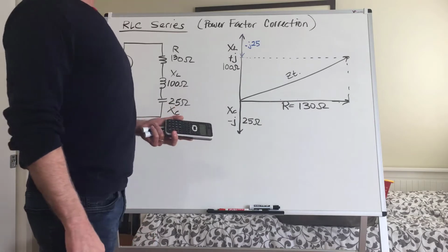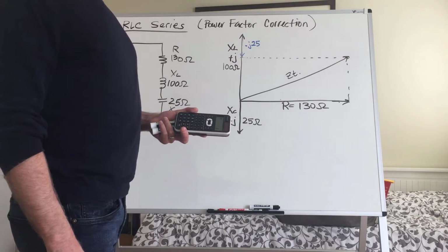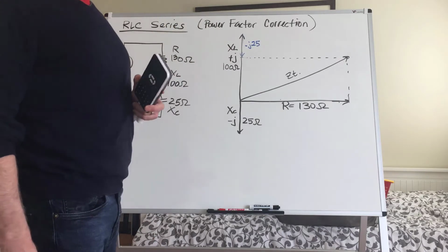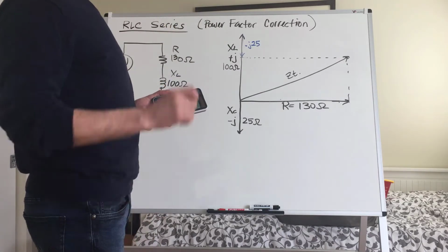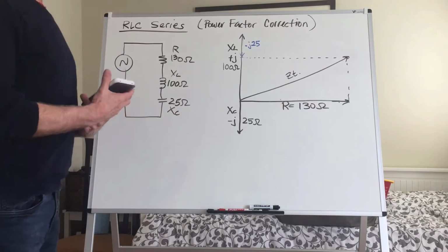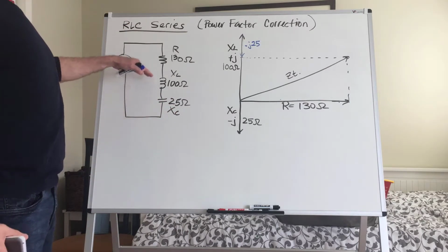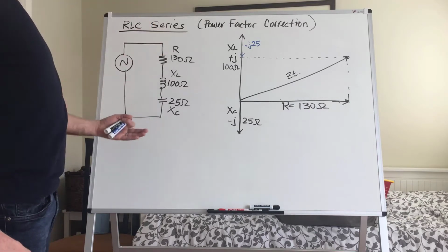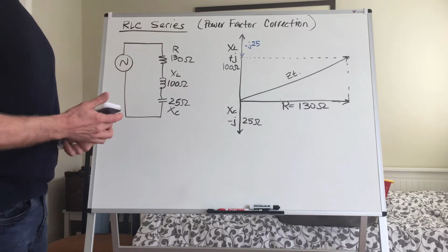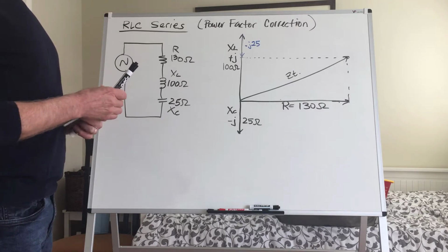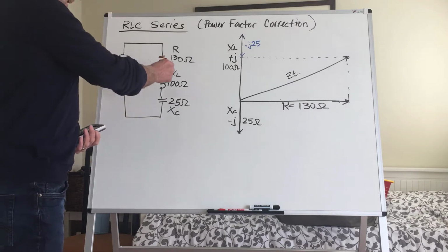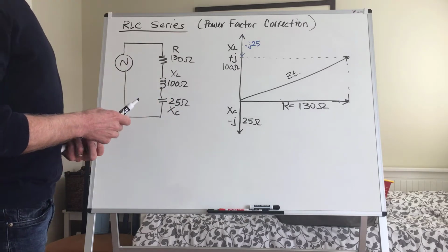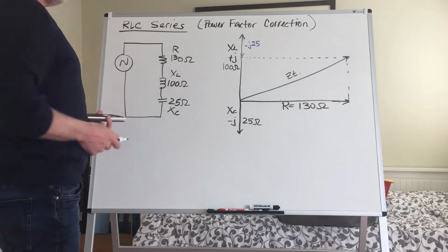And it's really not that difficult once you just boil it down to a common way of approaching purely series RLC. So let's take a look at this example. I've started out with an RLC and given it values of both reactance and resistance. Of course, if this was an example of a circuit that included an L value and a C value, you'd have to go through the proper equations to determine XL and XC.